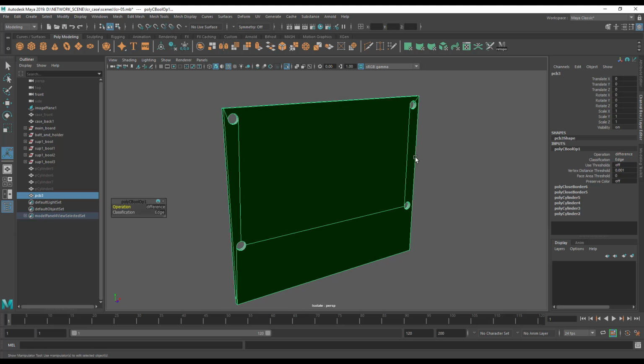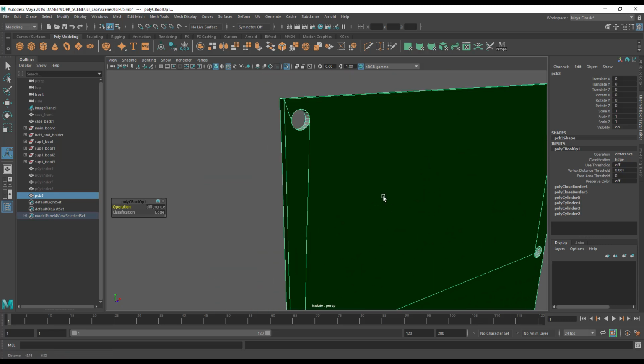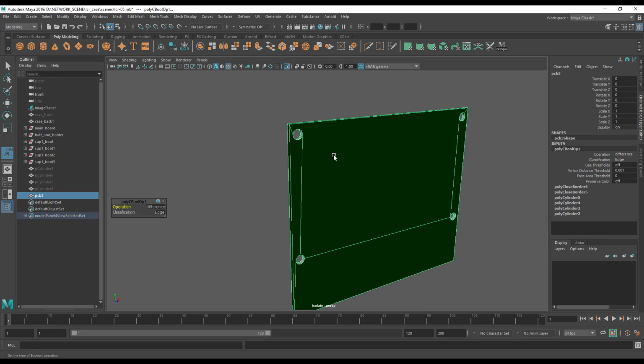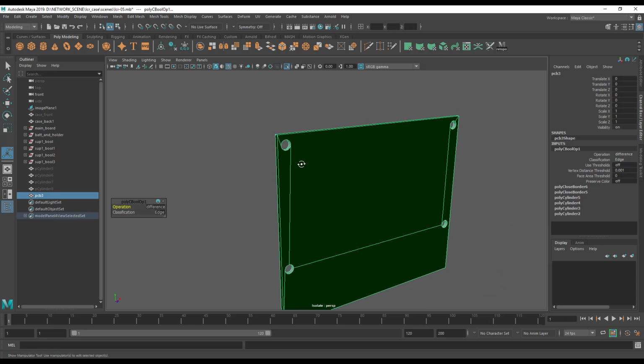Now, Boolean operations in Maya are not good compared to something like Rhino or SolidWorks. They have more of a tendency to error. You can use them, and more importantly from a Maya artist perspective, they leave behind hideous geometry. This is a huge n-gon. No CAD package will care about this. This will be the geometry that comes out of a CAD package.